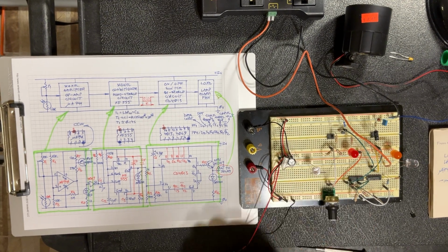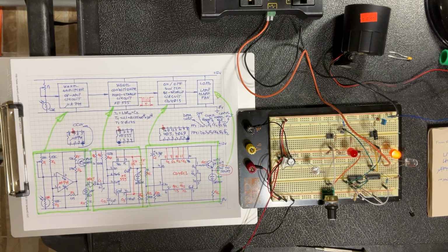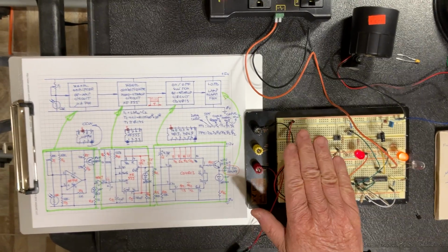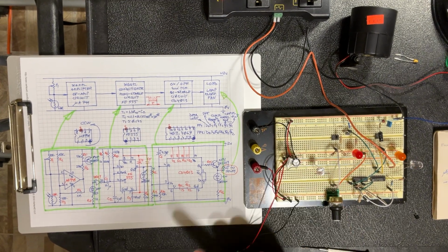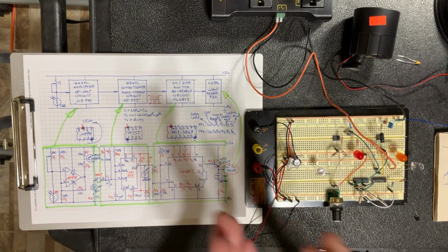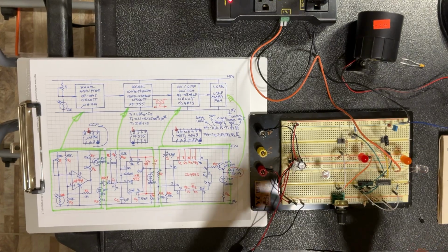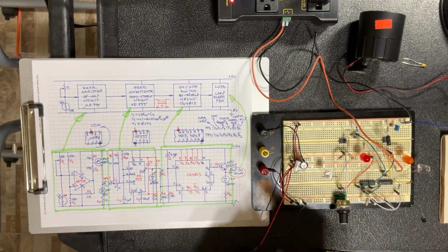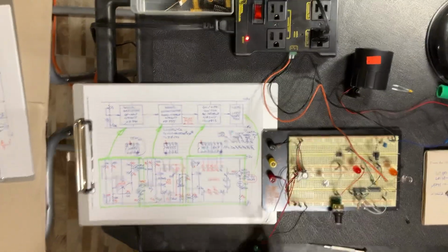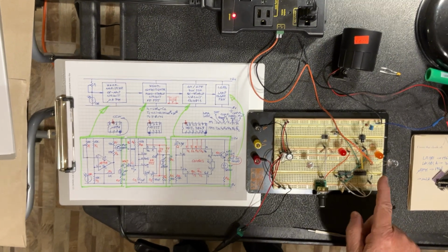So this is what I should do. 1.5 seconds. Or shortly, 1.5, 1.4 seconds. See? Shortly or longer, it won't matter. Or even if I give more pulses. So this is to prevent the last stage we're going to build a bit later from receiving more than one signal at a time, because we don't want the contacts of the relay to go on, off too many times, because otherwise they are going to wear out. So this is how this thing is working.